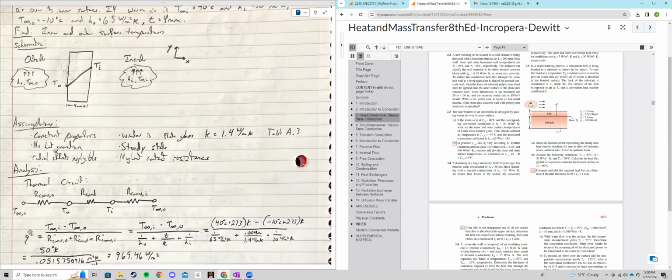Now, when using heat flux instead of just heat, we can then neglect area and just focus on the convection coefficients, the conduction coefficient, and also the thickness of the layer that we were trying to solve. This is going to help us because the problem did not give us any other area dependencies or surface area of the glass. So a breakdown of the equation again. We have the temperature difference as stated before, but now we have the actual values that we need to place inside of these equations.